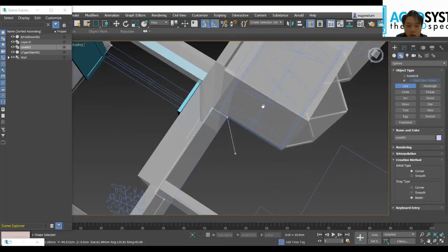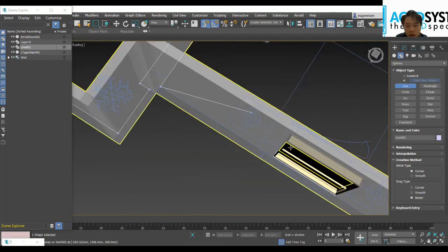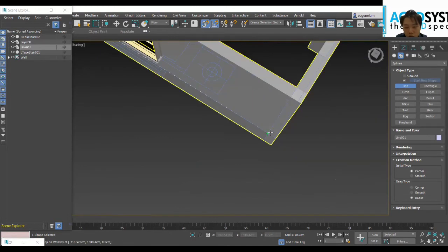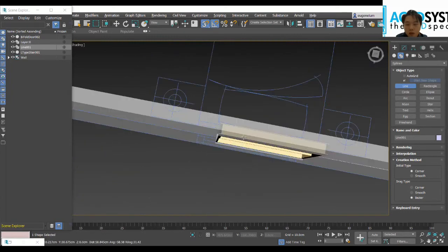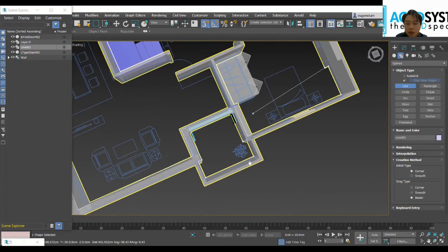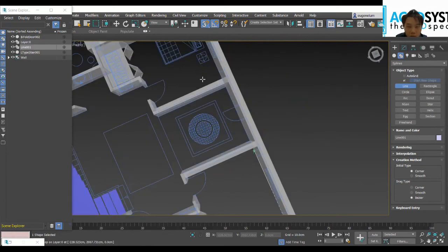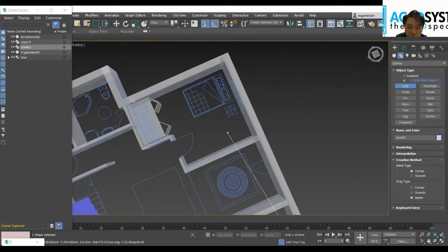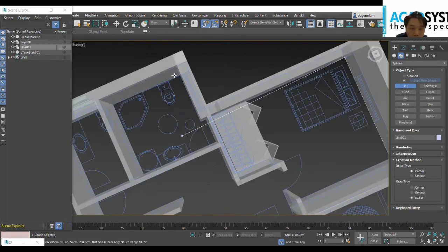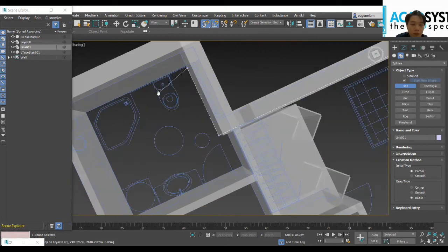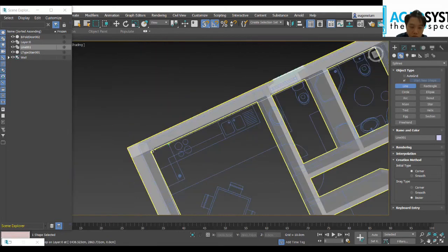Over here, choose the right point. Make sure you choose the correct point. If not, maybe there are some places they are not. There is blank. Oh, sorry. Okay. Just select endpoint. Okay, just join this spline together and click yes.